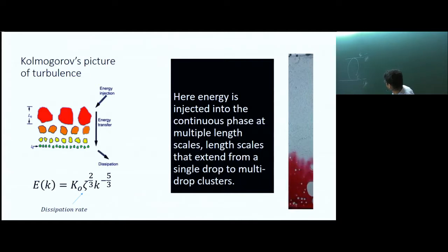Yeah, this is right. So you start having convective cells, and if you reach a perfect parameter, then you will have nice convective cells here. The difference between this and a pipe flow is this: in a pipe flow, your pressure term is the only forcing term that you have, whereas this is a buoyancy-driven system, and in a buoyancy-driven system the forcing term will come from your alpha times some gradient of temperature up here, because that's the density difference that you have. So the forcing term will depend upon the local temperature in the system. That's an additional term that you have.